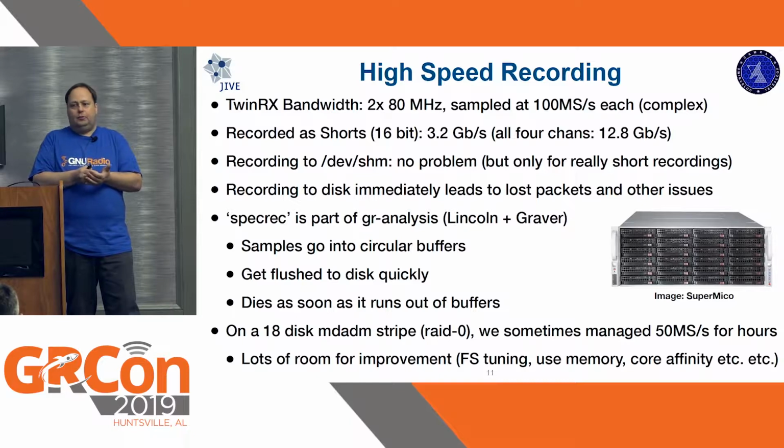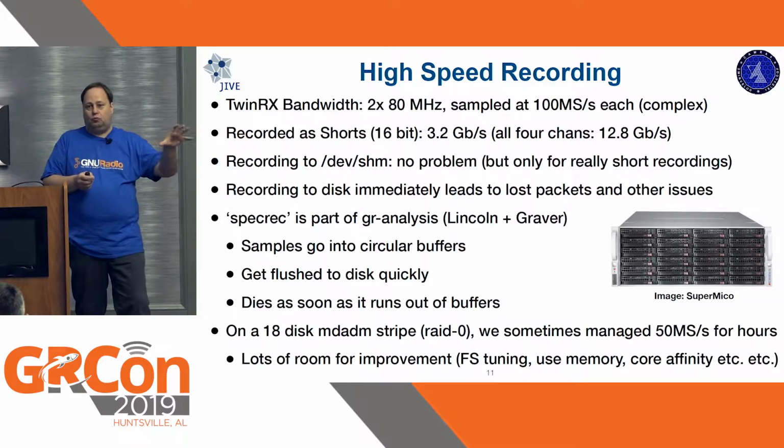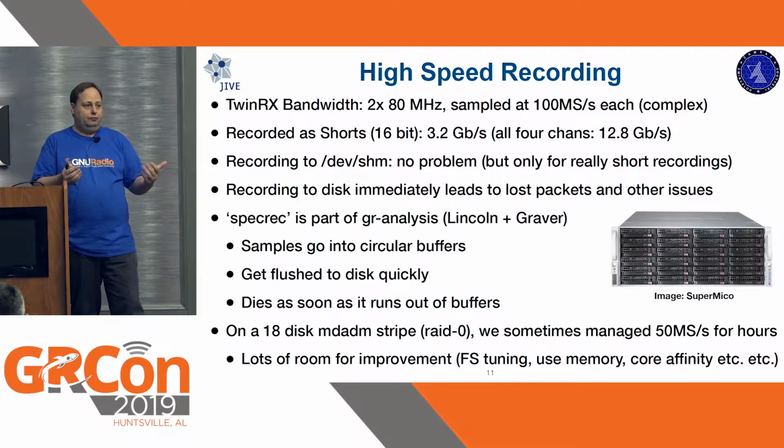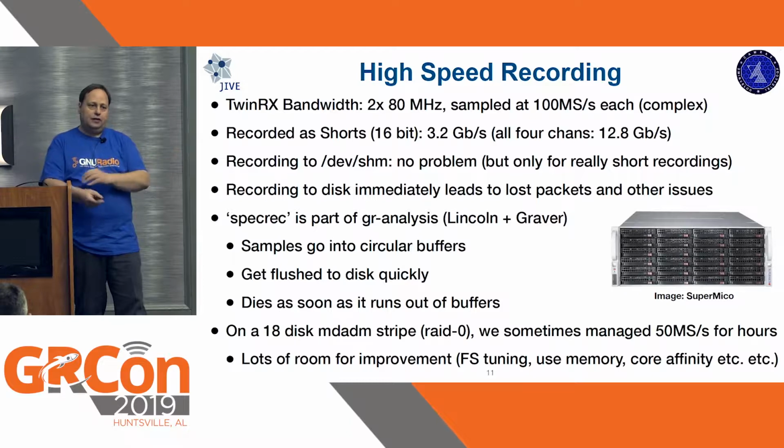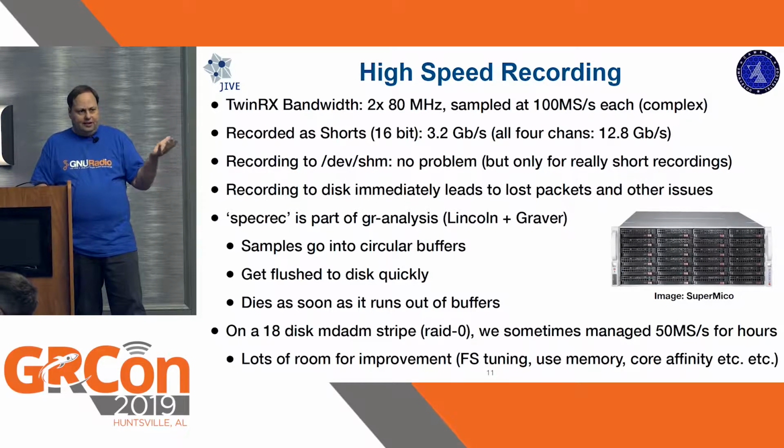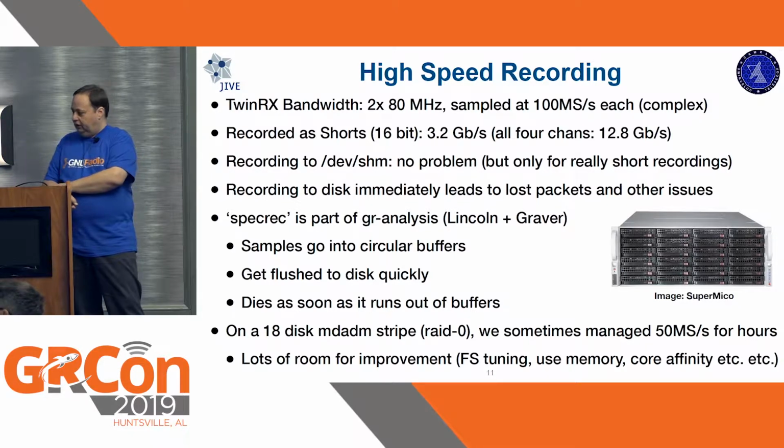And that does something a little bit more sensible, where you have a large ring buffer of memory that the thing records in, and at the same time writes to disk. It doesn't wait for it all to be filled and then write to disk, because then it's so busy writing to disk that it can't take the next samples. And with that, at least at 50 megasamples per second on just one port, it would keep up for hours sometimes, often not. Anyway, if there are people who have better ways of recording this, let me know.